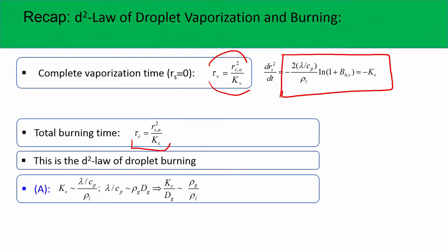So, it is imperative that you produce very small droplets inside the combustor. To understand that, we are fortunate in one sense that even if we send out a liquid jet, the liquid jet is not a very stable configuration. A liquid cylindrical jet is not the stable configuration, because we will show that the liquid jet tends to minimize the surface energy, and so tends to form droplets, with a size proportional to the radius of that jet. We will see how that happens.